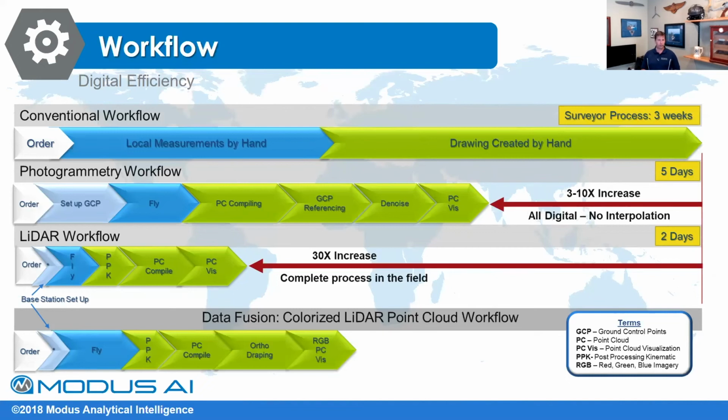And I just threw in the bottom, because this is kind of a photogrammetry versus LiDAR slide, even though it's really not meant to be. If you do need colorized data and you're doing dual sample, you can do a draping, and that will get you your visualization data. So it's still a little faster than photogrammetry. But if you're trying to get RGB clouds, do photogrammetry in addition.